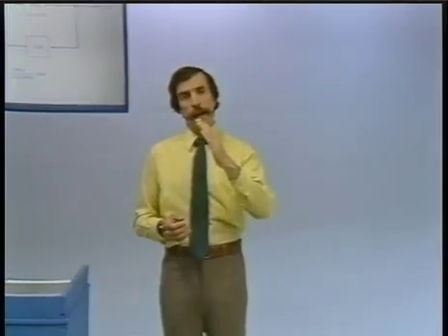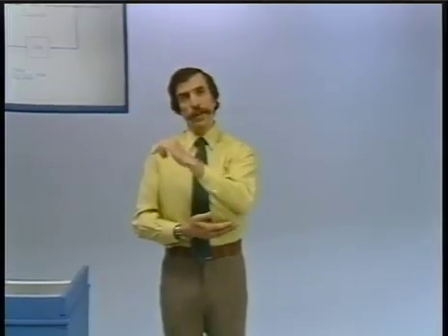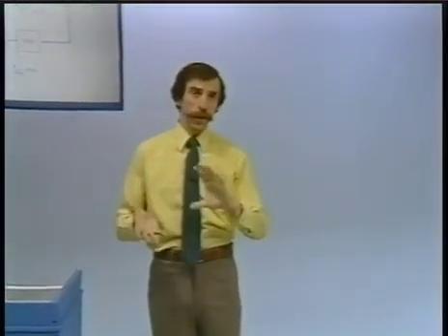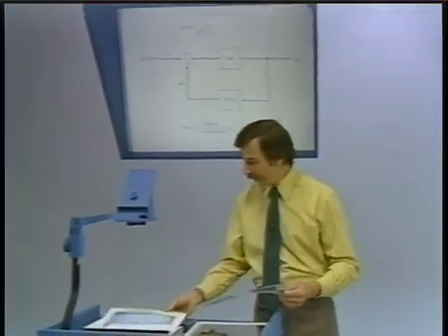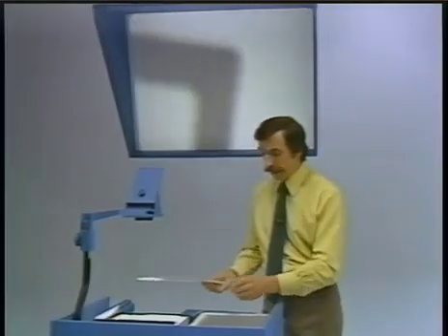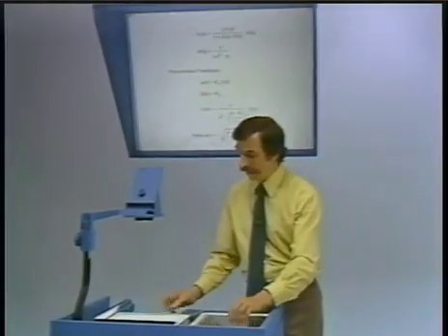Let's take the angular measurement and feed that back, say through a potentiometer and perhaps an amplifier so that there's some gain, and see if we can stabilize the system simply through feedback which is proportional to a measurement of the angle, what is typically referred to as proportional feedback. Well, let's analyze the result of doing that.